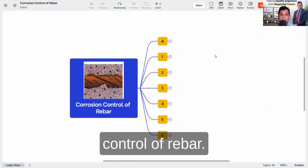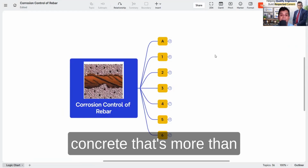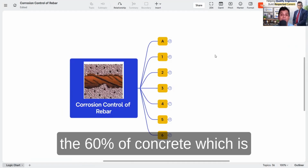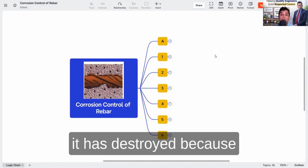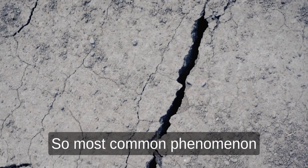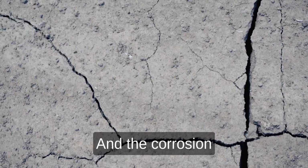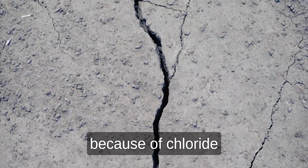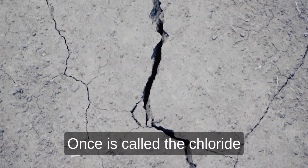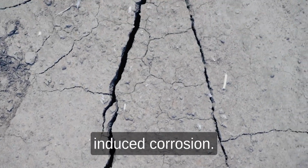The subject is corrosion control of rebar. Now it's a problem of every concrete. More than 60% of concrete which is deteriorated or destroyed is because of the corrosion of the steel. So the most common phenomenon is the corrosion of the steel, and the corrosion of the steel happens mainly because of chloride and carbon dioxide. One is called chloride induced corrosion and another is carbonation induced corrosion.